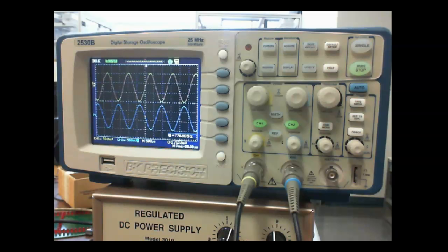They're 180 degrees out of phase, because when the input goes up, the transistor turns on more, causing it to drop more voltage. So the only disadvantage, and it's not really a disadvantage as far as audio is concerned, is that your input and output on this amplifier are 180 degrees apart.